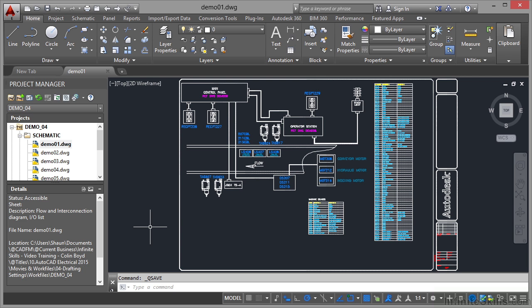in your project manager in AutoCAD electrical. Now, the object snap settings are available in the status bar in the drafting settings at the bottom of the screen. It's this icon here. So there's your snap cursor to 2D reference points. It's on, and as you can see, it's called Object Snap or OSNAP, and it's the F3 function key that switches it off and on.